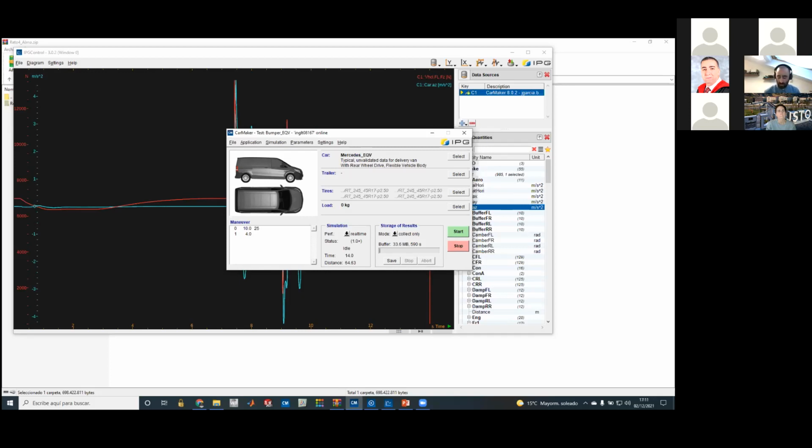Great. I will go for them. So the first question was regarding that the excitation of the engine is usually measured in terms of the RPM of the engine. Here, the key point is that the comfort is felt between 0 and 10 Hertz. The key point of comfort, the overall comfort we perceive, is between 0 and 10 Hertz. The excitation coming from the engine is above this.